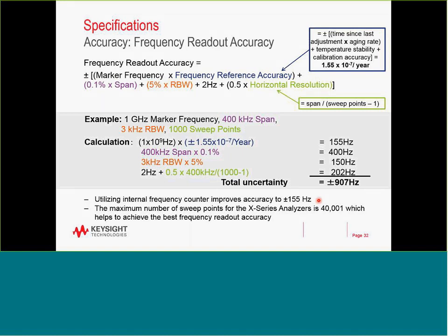So if you take one thing out of this seminar or this webcast, please go find how to use the frequency counter on your equipment, because that's what you should be using if you want to measure the signal frequency accurately.